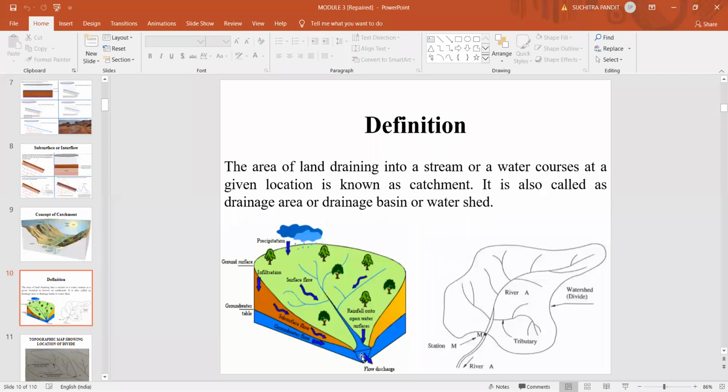You already know how to calculate the discharge in open channel flow from the fluid mechanics laboratory, and the procedure is almost similar here, since you have gravity flow from higher elevation to lower elevation. The point where you measure the entire discharge from the catchment area is called the concentration point.